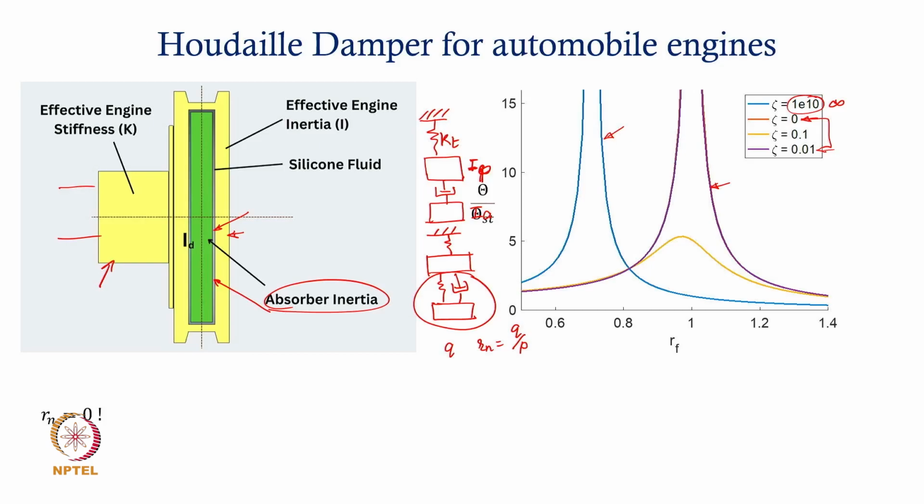So it would be interesting to understand why you get lower resonance frequency for zeta equal to infinity compared to when zeta is equal to 0. We partly discussed this in the earlier discussion, okay. Zeta infinity means these two are actually getting clubbed together. The two masses will club together, and then you will have a single degree of freedom system, and the mass being heavier or larger, your frequency will drop, it will be lower.